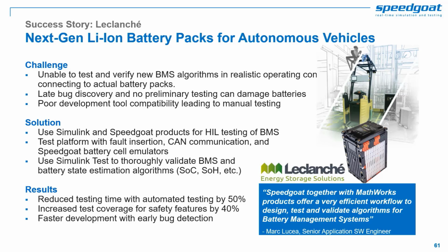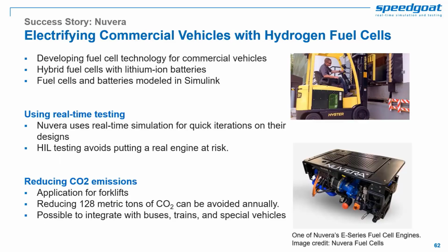As is typically required, such tests also required fault insertion and a communication protocol like CAN. They were able to thoroughly validate their BMS and state estimation algorithms using Speedgoat real-time solutions, thus reducing test time by around 50%, increasing coverage, and finding bugs at an early stage.